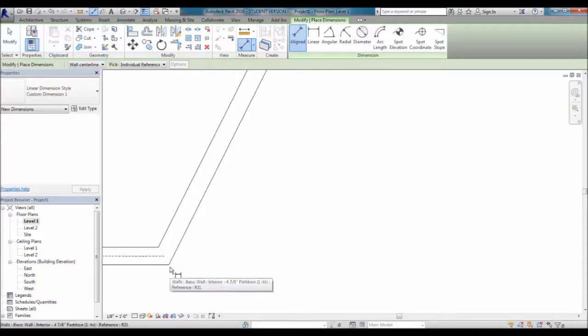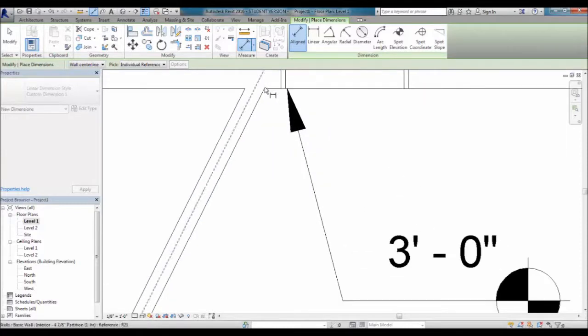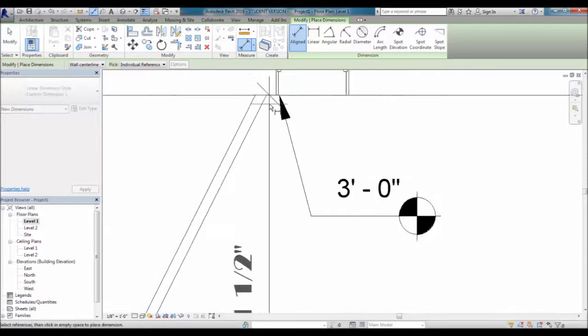In my case it was 3 tabs after the hover, which gets me to this point here. Basically you want it to be selecting the little point on the very corner of this wall. If you can get it to that with the Tab key, then left click to select it. You're going to want to do the same up here, where these two are connecting, so tab through until we select that point.